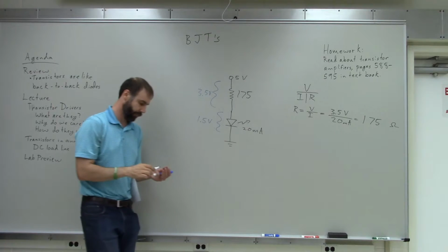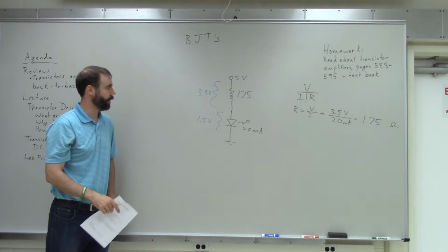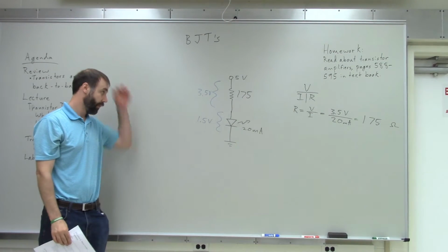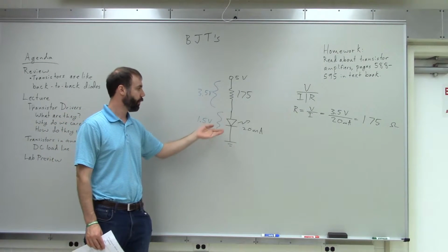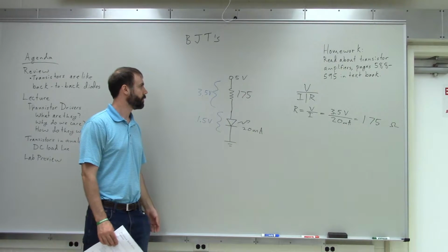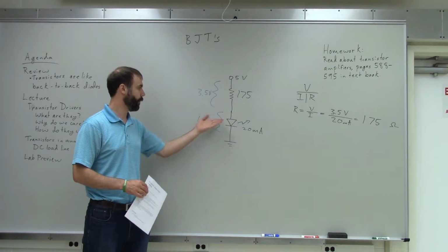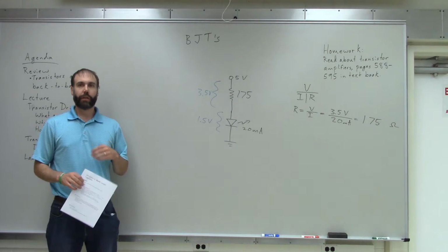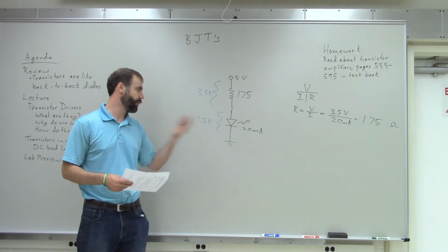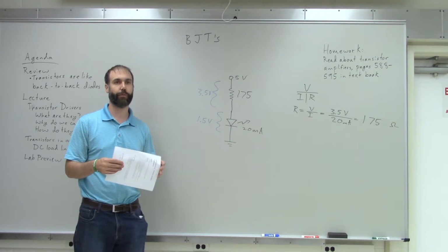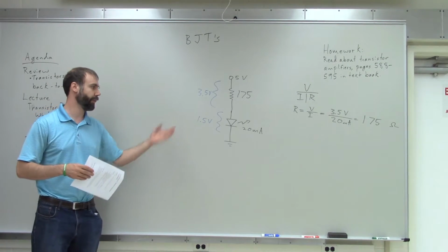All right, so cool. So the first thing that we would do if we were trying to power this LED is we would build a circuit that looks like this. And we know that when we hook up this circuit, we'll get 20 milliamps flowing through that LED, right? Why 20? If you look at the data sheet for a lot of LEDs, 20 milliamps is sort of right in the middle of the range of what is acceptable. So you could have a little more and it'll be a little brighter, or a little less, it'll be a little dimmer, but that's a pretty standard value.